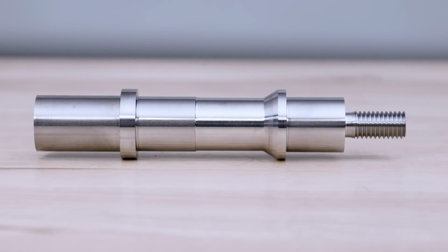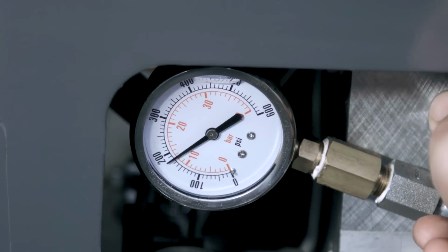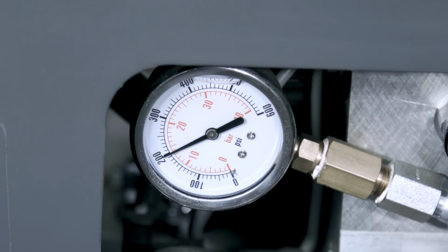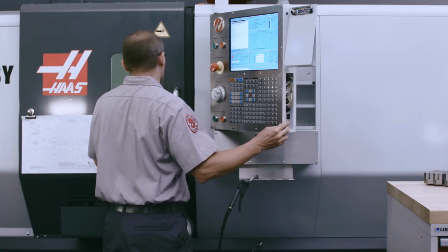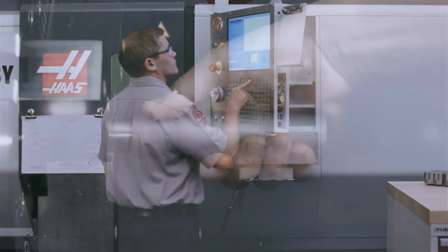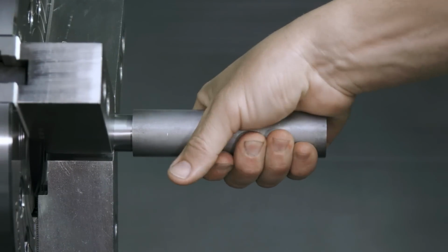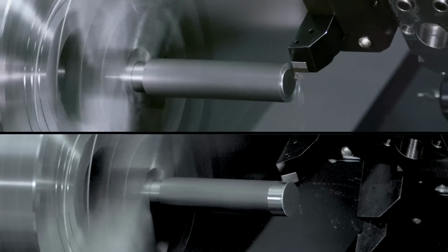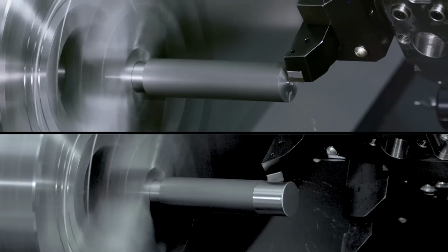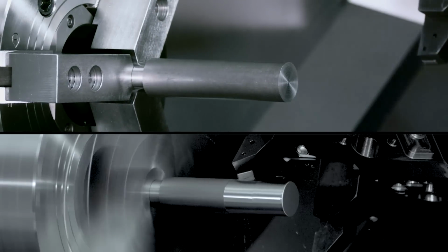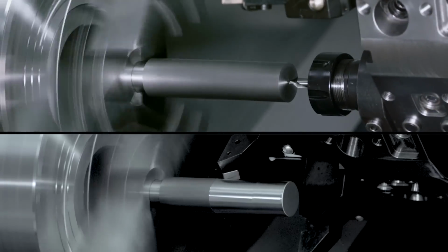Okay, can we make our part now? You bet. Let's return to the profiled and threaded shaft we looked at the beginning of the video. We'll use a tailstock pressure of 200 psi, since we know this is more than sufficient to keep our part in place without any unnecessary amount of force on our part and machine. With all the aspects of our tailstock support accounted for, we're ready to run our program. But instead of just watching this part run with the tailstock supporting it, we thought it'd be a good idea to watch how it performs running alongside a separate run made without the benefit of tailstock support.